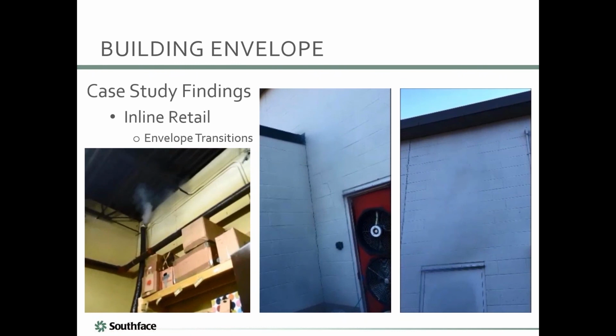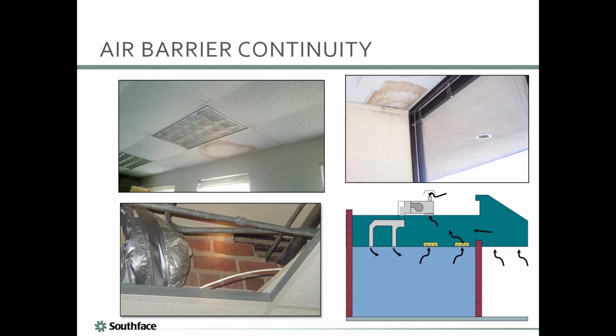And then lastly, just thinking about the impact of not doing these details right, and what kind of failures we see besides a huge amount of energy waste. Particularly in the South, we have issues with moisture, and that adds to the energy load. It's a lot harder to dry air because of all the humidity that we've let in, but it also causes these kinds of moisture damages. So this is the hole. This is often under negative pressure because it's a duct. We suck in humid outside air. It drips on something, and that's the failure that we're looking at.